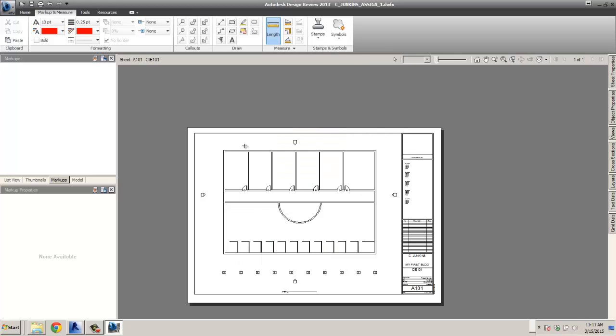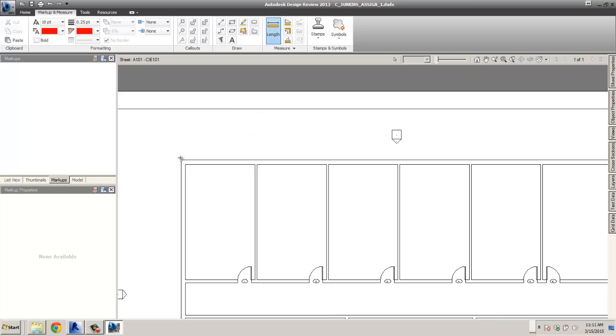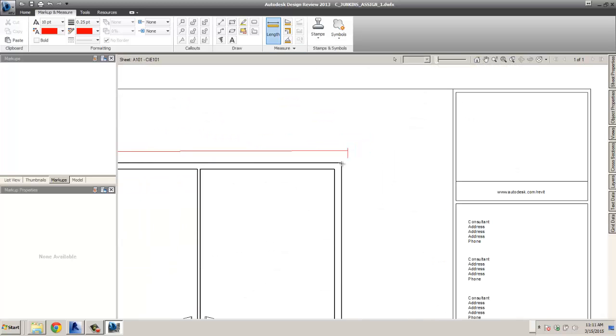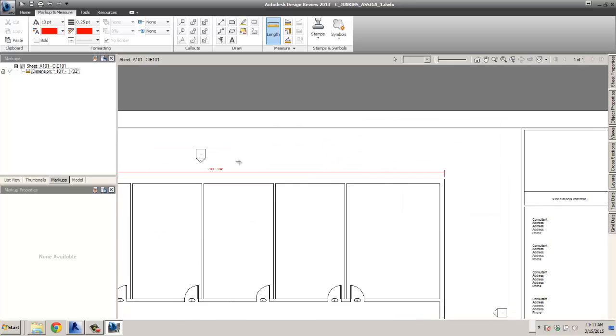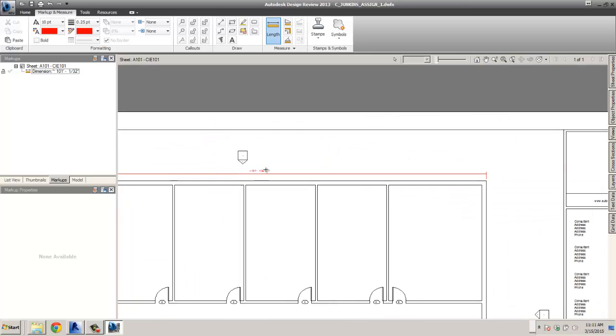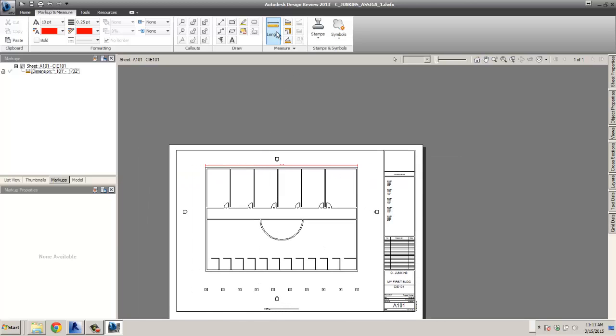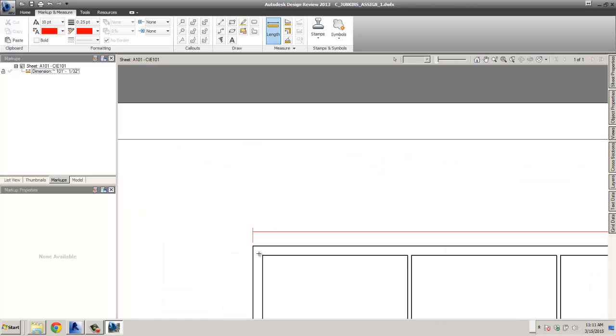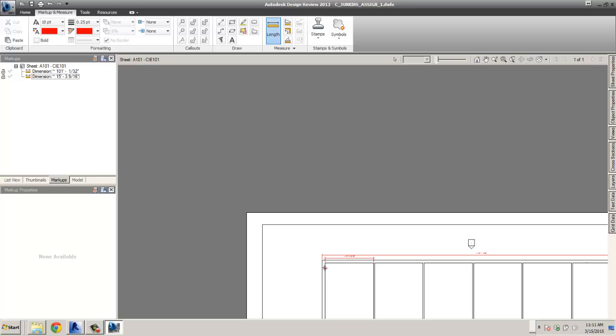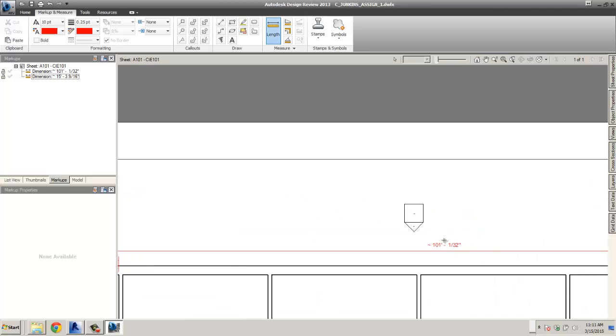We'll say OK. So now if I sent this to an architect or engineer, I want to measure from this point to this point. It's 101 feet, 0.132 inch because of the wall thickness. If I actually measured from inside this wall to this point, because remember I put this in from center line, so the actual center line dimensions are 100 feet.